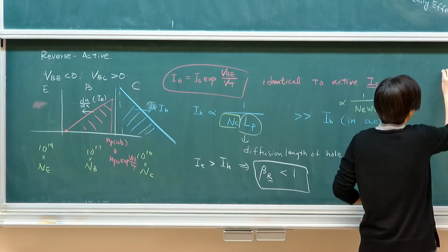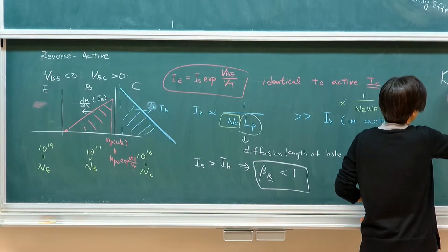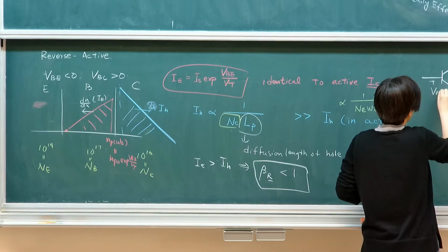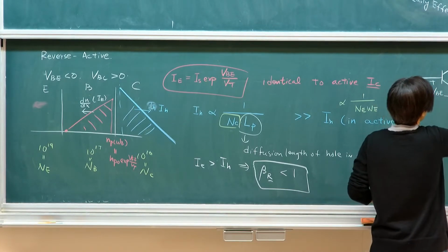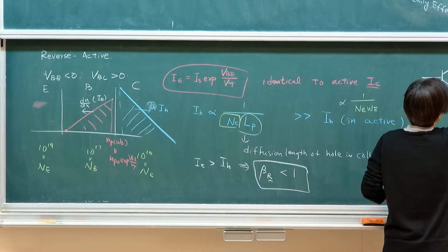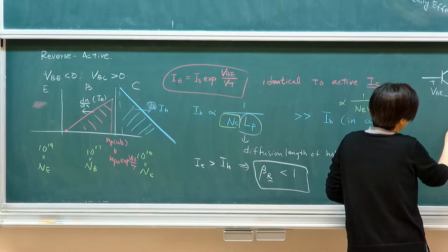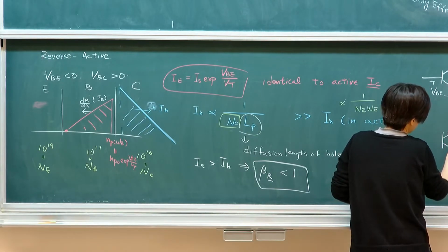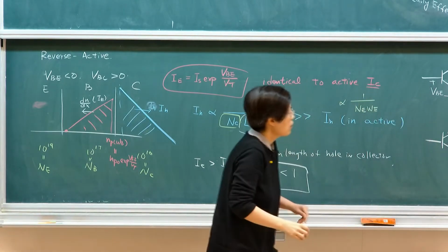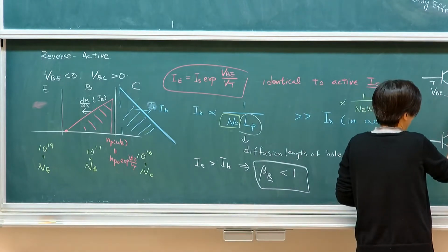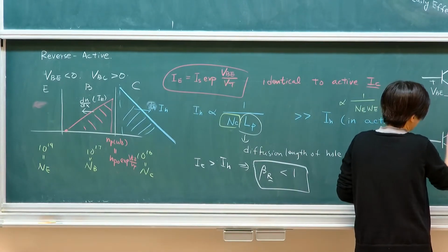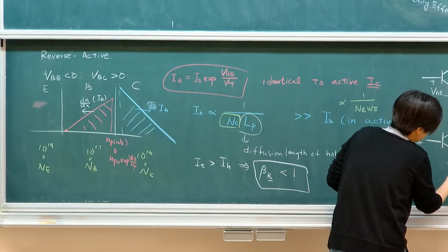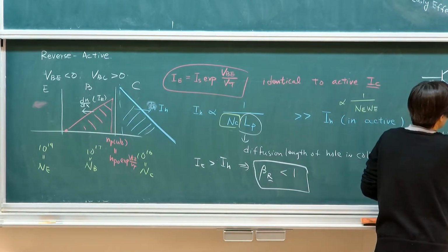It's very hard because it typically wouldn't work this way. So let's say this is forward active. This is forward. In reverse, what happens is that you flip the device, so it will be something more like this. If I'm putting this at a high voltage, say VCC, this is 0.8. If I operate this way, this is 0 volt. So this is called a reverse active.